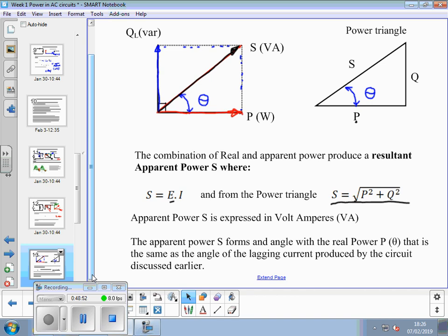The apparent power gives you what current is going to be drawn from the source, the generator or the power supply. That includes the portion that is delivering the magnetism to magnetize the transformer core, as well as the P part, the watts that are going to do work.